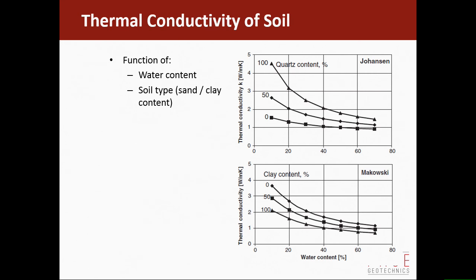And there are some charts published which we can use to estimate the thermal conductivity of the soil. You can see here with both of these charts, and they're actually quite similar. Quartz content, if it's 100% quartz content, that implies it's sand, so that would have zero clay content, close to 100% sand content.